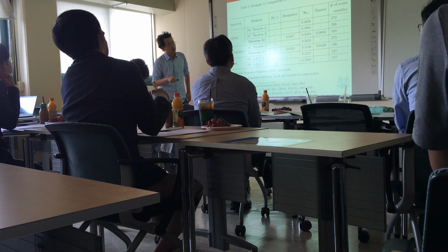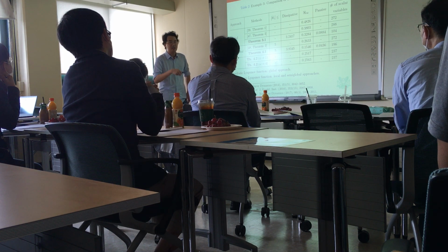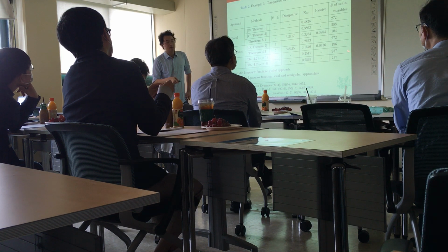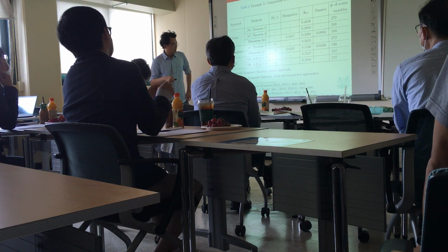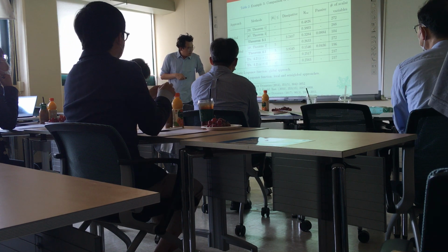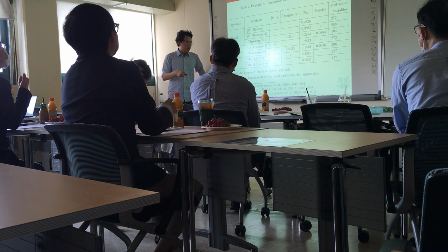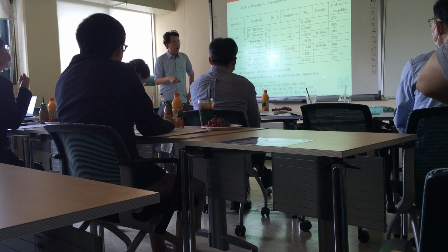Can you see that? This H-infinity performance is better, and we also require fewer scalar variables. Here you see that a quadratic Lyapunov function is designed in the global approach, while non-quadratic Lyapunov functions are designed in the local and semi-global approaches.